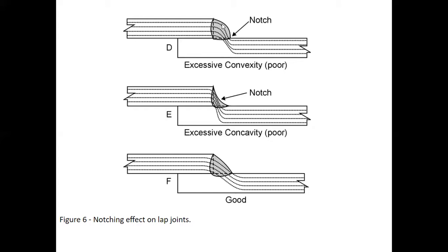That could be adjusting our amperage on our rod, maybe turning it down just a little bit so we have more control over it. Things like that. Basically keeping a shorter arc, keeping your arc tight into the plates. That'll help control this big belly on the front. Keeping that longer arc is going to allow that belly to fall out and get big. And then that changes the profile, creates something we don't want here. Here is a bit of a notch effect. It's done with a concave weld.